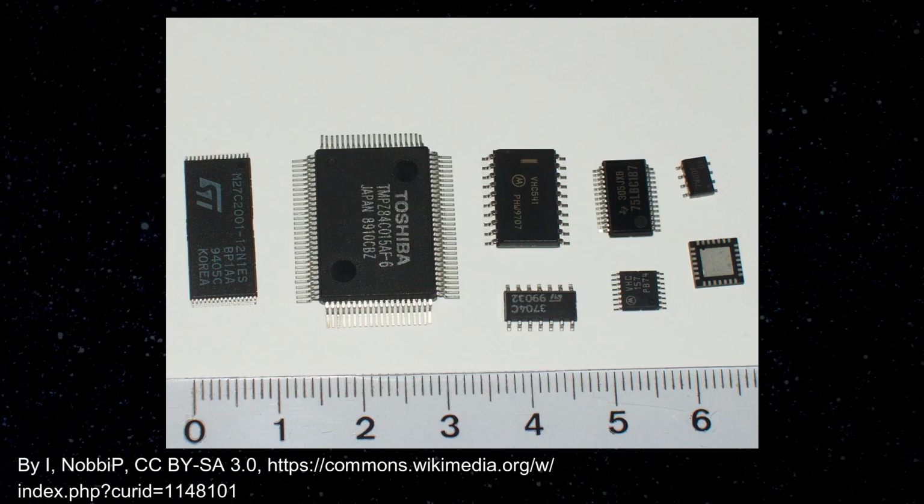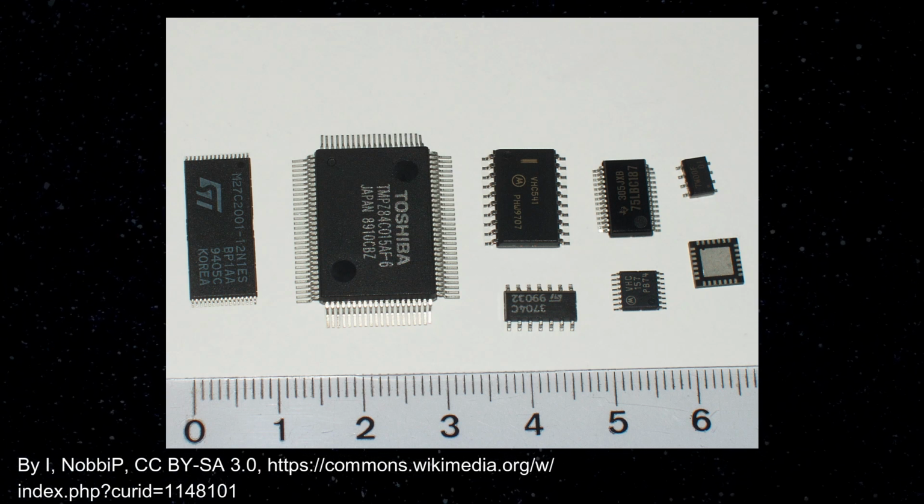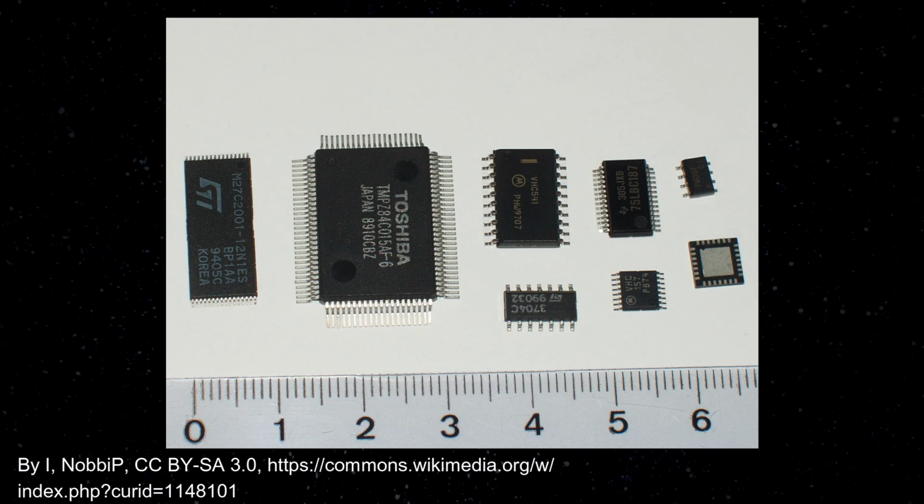ICs are incredibly complex. The individual components are embedded directly into the silicon crystal instead of just being mounted on top of it, and the wafer and copper layers are very thin and fragile. The IC die is far too small for anything to be connected to or soldered onto it, which is why we package the die into a black chip that forms the basis of hundreds of electronic devices. The package encases the IC die and allows us to more easily connect it to devices. The pins on the outside connect to other parts of a circuit.